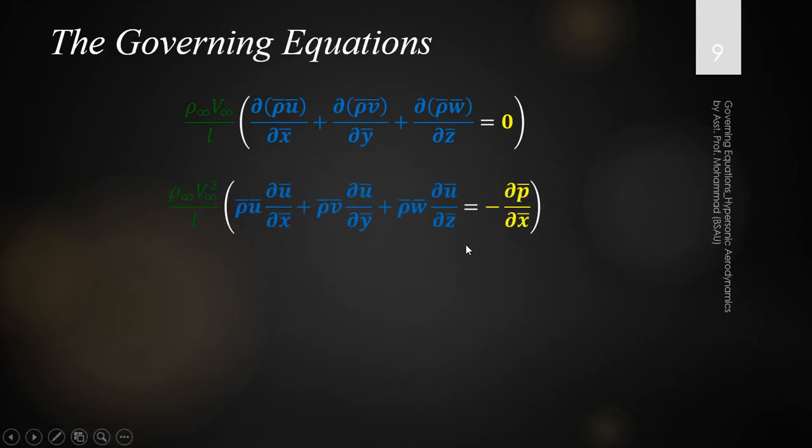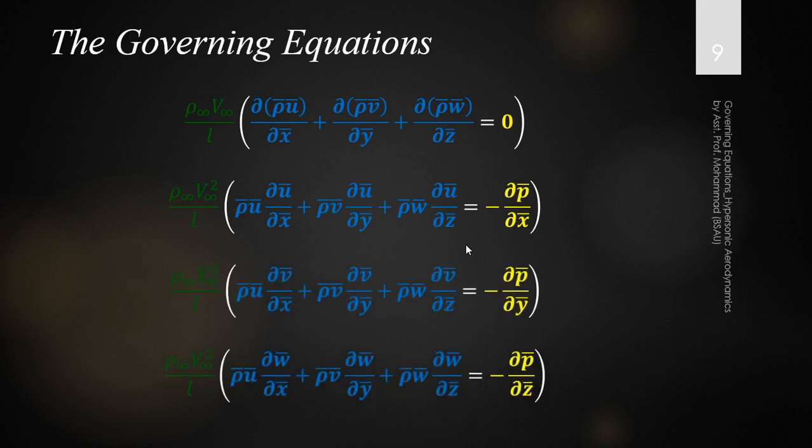Now the momentum equations. These are the momentum equations in the x, y and z directions, and they have this as a factor. Students can try it; I'll give a little demo of how this comes out. You will find it advantageous that this becomes the common factor for the entire equation, and that's why you will realize why we took rho v square as the non-dimensionalizing reference expression for the pressure. Let us see how it goes ahead.